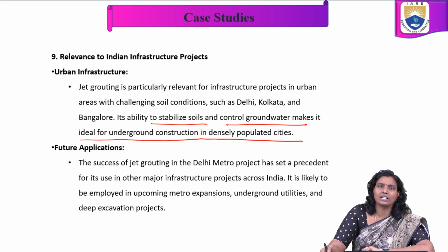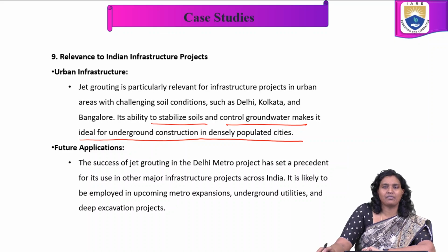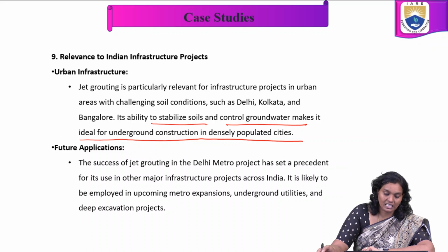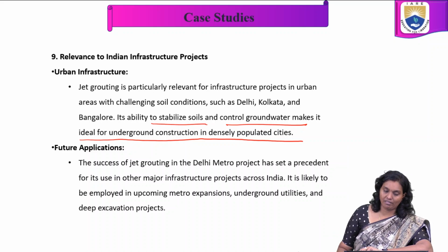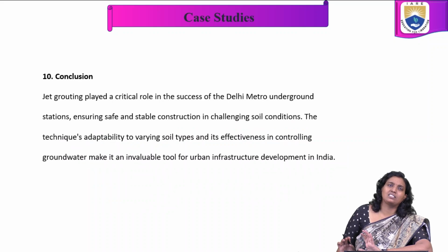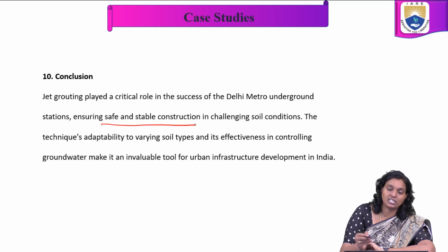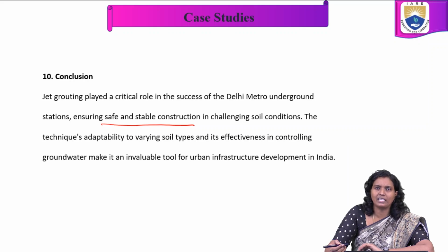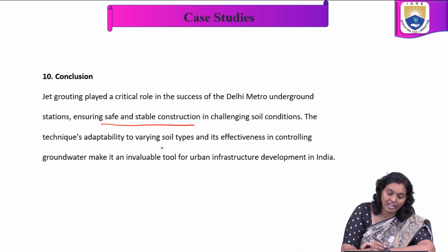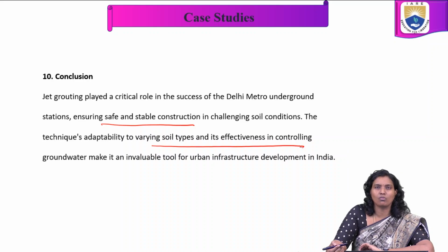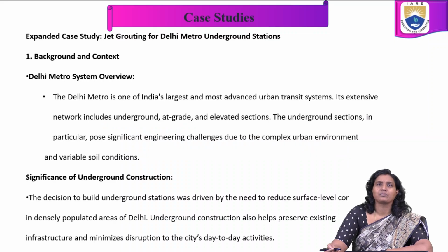The success of jet grouting in the Delhi Metro project has set a precedent for its use in other major infrastructure projects across India. It's likely to be employed in upcoming metro expansions, underground utilities and deep excavation projects. Jet grouting played a critical role in the success of Delhi Metro underground stations, ensuring safe and stable construction in challenging soil conditions. The technique's adaptability to varying soil types and effectiveness in controlling groundwater make it an invaluable tool for urban infrastructure development in India.